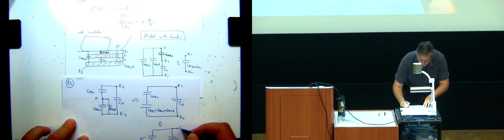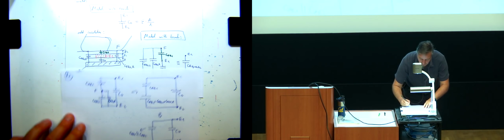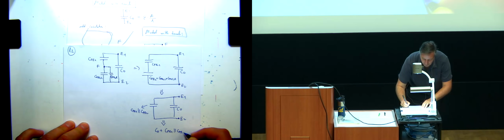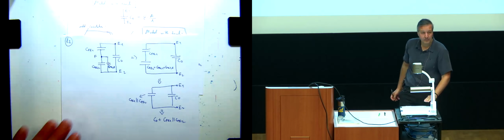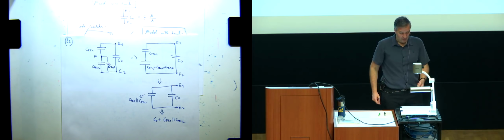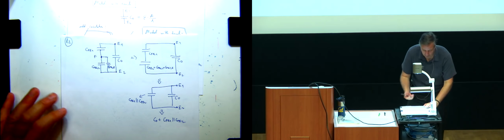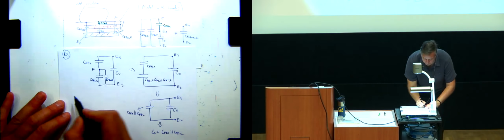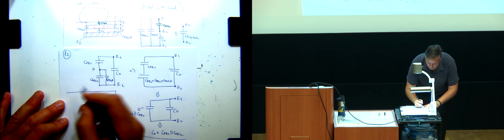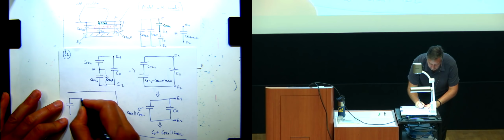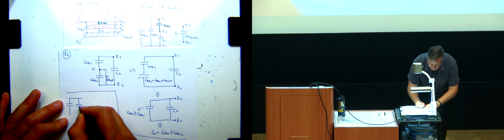These nodes are still E1, E2, right? And then that finally is just one capacitor, which is C0 plus CF E1 parallel CF E2. Right? Does that make sense? That's kind of easy when I redraw it like this, but you can also just go from the drawing that we did previously. So let's just do that if people are confused still.